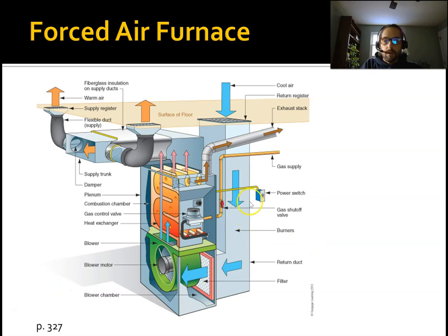There are some minor components like your power switch, your gas shutoff valve, the gas control valve, and some other components. But that's the basic premise. Now there are different types of heating systems. This is a lower efficiency furnace. It's not a condensing furnace, but the basic process is going to be the same.